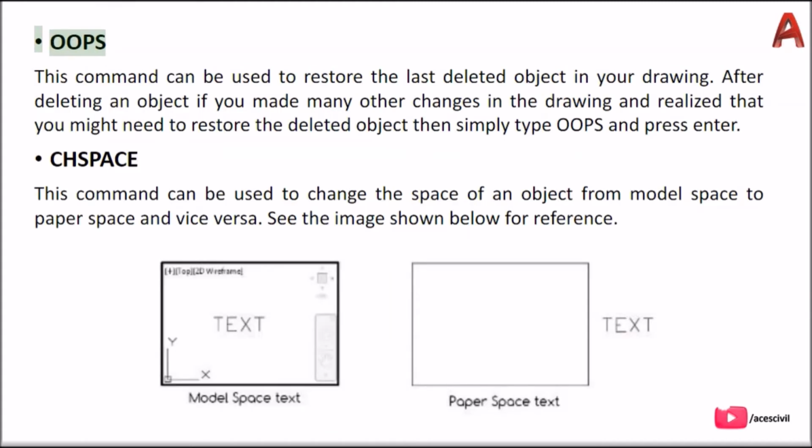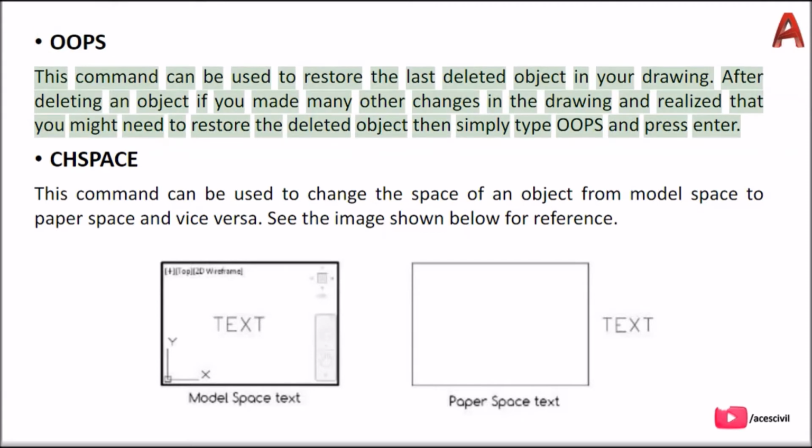Oops. This command can be used to restore the last deleted object in your drawing. After deleting an object, if you made many other changes in the drawing and realized that you might need to restore the deleted object, then simply type oops and press Enter.